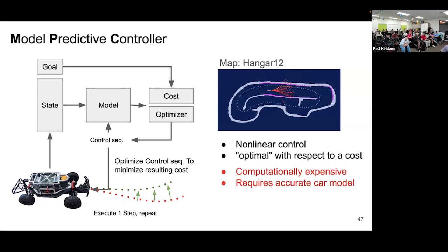How do you do the optimization to find the smart one? Just sample multiple ones and take the best one? That's one way for an optimizer. Actually here, this is called the MPPI optimizer, model predictive path integral, where you try thousands of sequences and then you weight all of them and average by the exponential cost. And that's how you get quite a simple algorithm to get pretty nice optimal control if you have a lot of computational power. The car is kind of limited, but MPPI with maybe 500 of these rollout trajectories runs nicely.